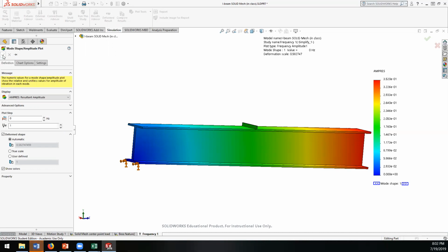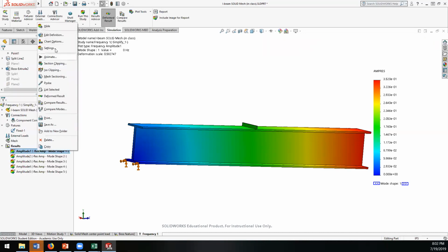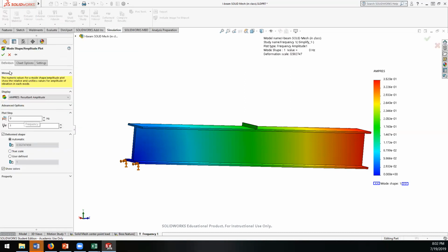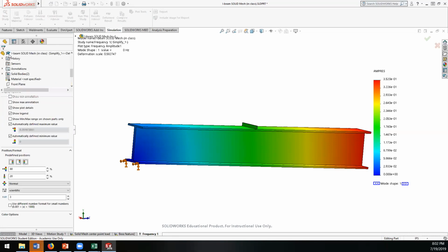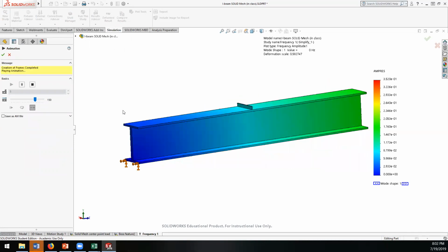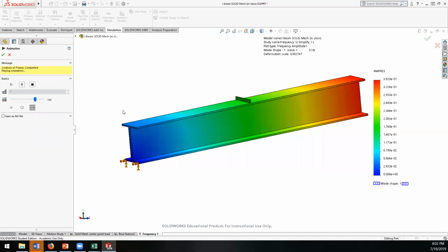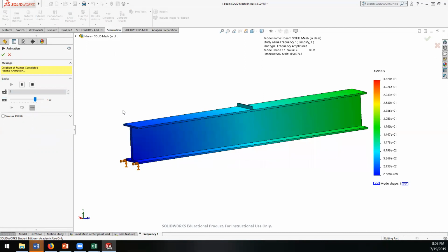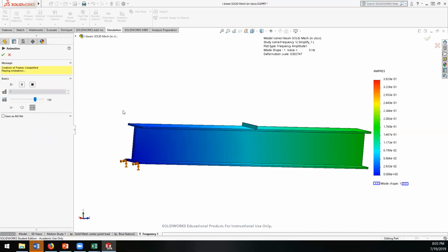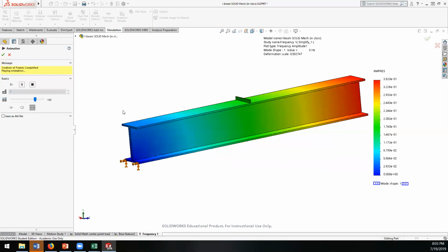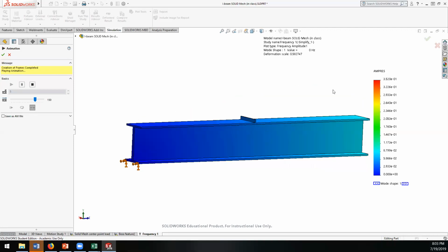If you activate this mode, if you animate it, that's the degree of freedom, right? It's pivoting about this point, which is what we wanted to do. We just didn't pivot the other end, right? But if you thought this was fixed, you wouldn't see this space moving at all. So this tells me, oh, I'm under constraint. I can rotate about this, okay?